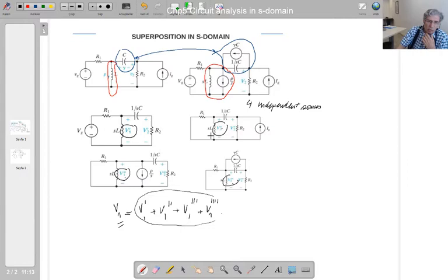What I mean is this. Let's say a circuit is given to you, the last circuit, let's assume this circuit. If I ask you what is the solution of the circuit if I replace these independent sources' values with double the value, that means, let's say, 5 times. This theorem tells me whatever you found before is going to be multiplied by 5 for the solution of this circuit. Why am I saying so? Consider a simple form of it.